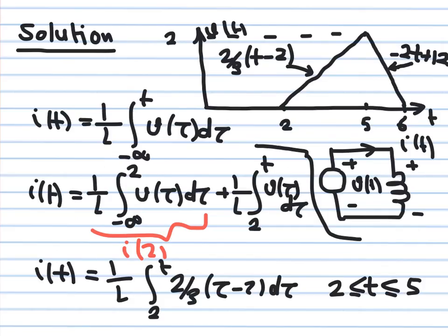Okay, first what I started with, I wrote an expression for this graph here. This is a linear graph. The current, the voltage, sorry, this is the voltage. It increases gradually from 0 up to 2 volts between 2 and 5 seconds. So you can find the expression of this line. The voltage here is simply equal to 2 over 3 t minus 2.